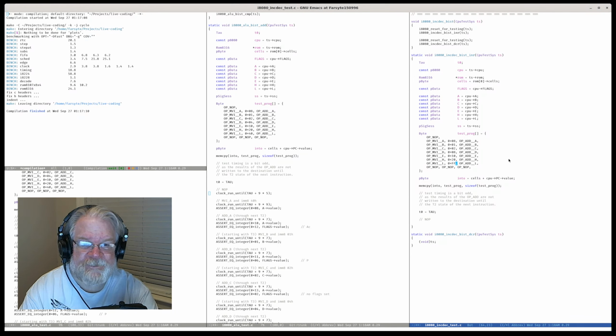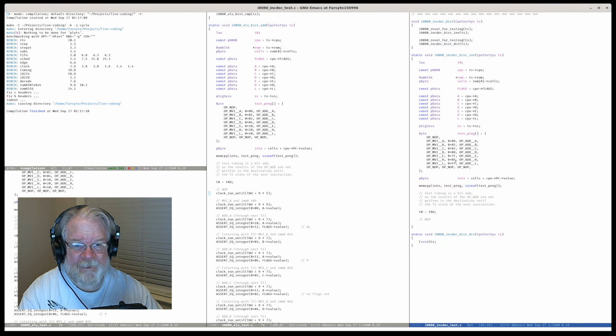This will be carry and 0, half carry. I want something to increment to be negative. I'll do 7F here, so increment to 80 and be negative. So I'll do 7F there, and I'll do BF there. So these guys end in F. They're all going to have auxiliary carries set as well.